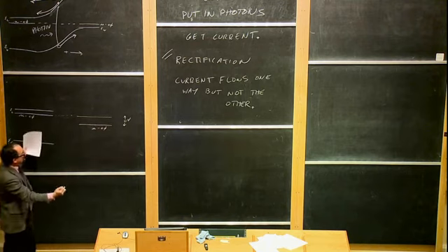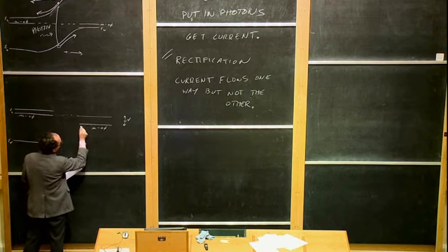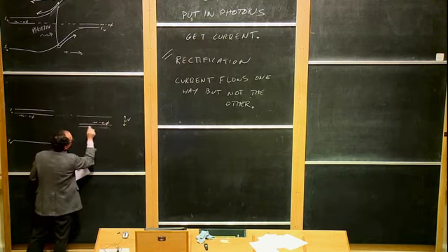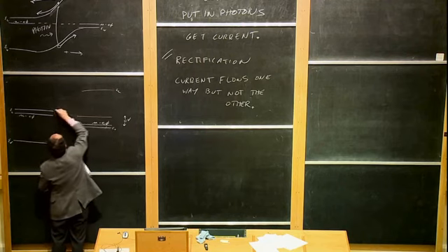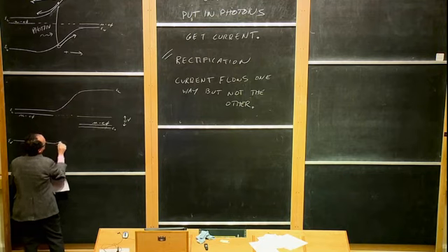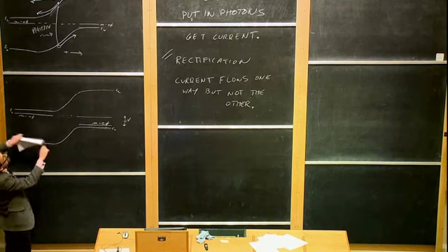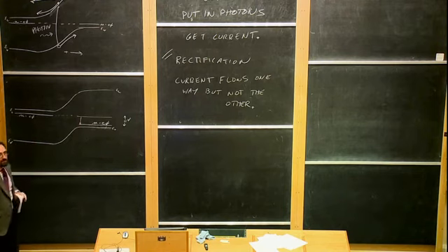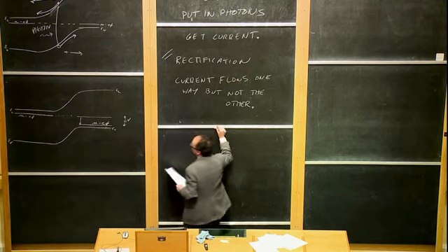So now, because I'm putting a voltage across the whole thing, we have to put in the valence band energy, mu minus E phi here, and the valence band energy is here, E valence, and then the conduction band energy will be up here. Conduction. Then in the depletion region, you have an electric field, which connects these together like that. Okay, so is it clear what I've drawn here? I've taken exactly the same picture. I've just applied a voltage across the two to shift this chemical potential down to here. Good? All right. So now that I've applied this voltage, how much current flows?